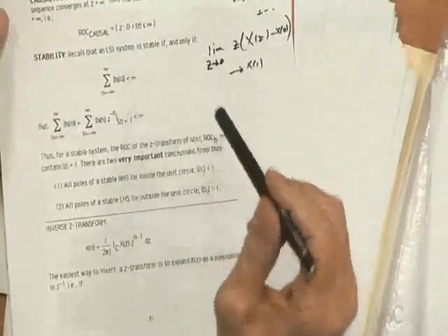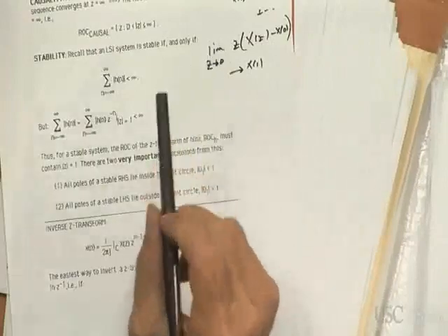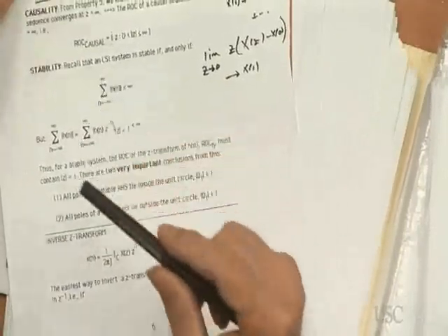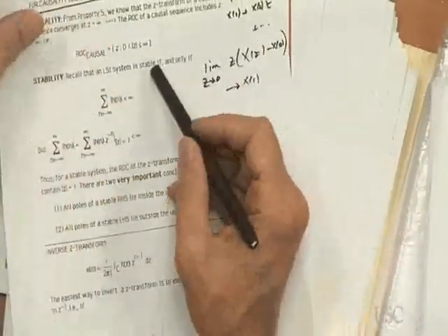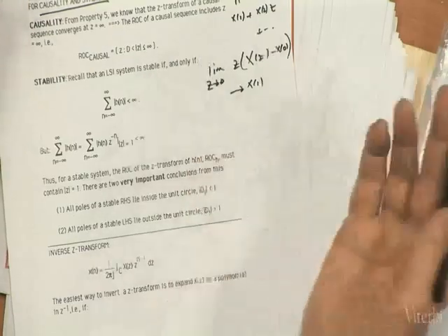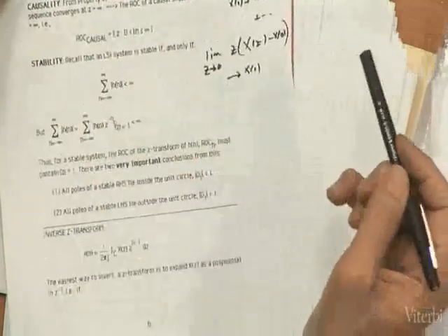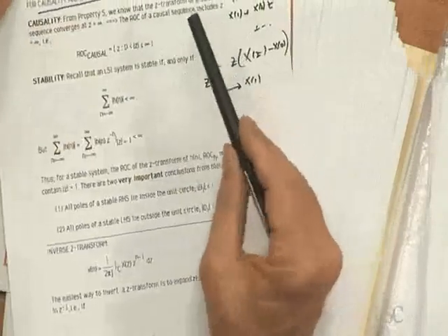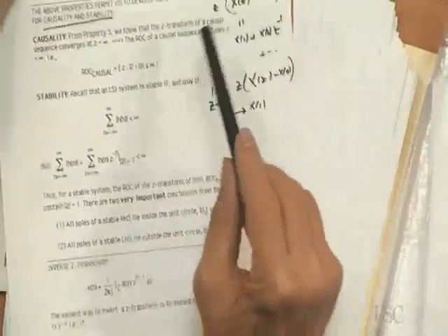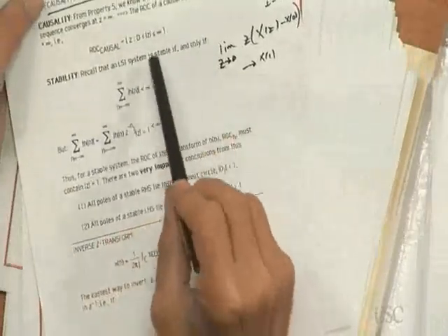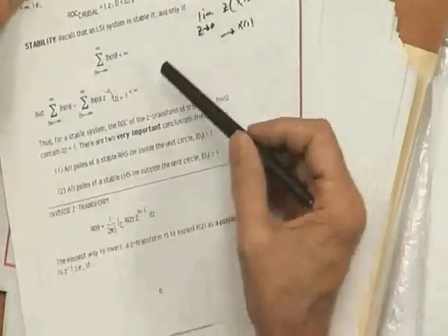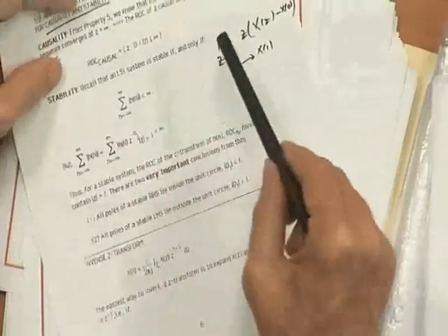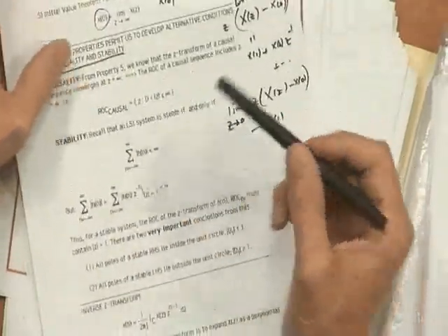If it doesn't, in other words, if the z transform includes positive powers of z, that's saying that the sequence doesn't equal 0 for n less than 0, or it could be left-sided. But anyway, for either left-sided sequences or non-causal right-sided sequences, if you let z go to infinity, H of z won't converge. So that's one way to tell about causality from looking at the z transform.